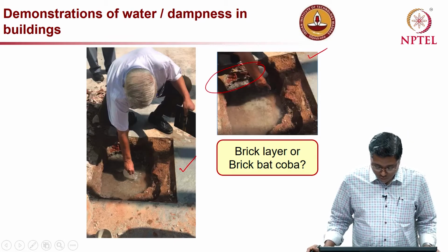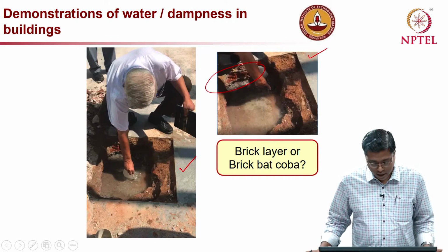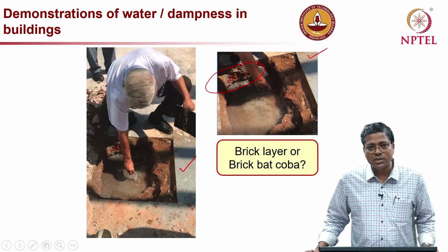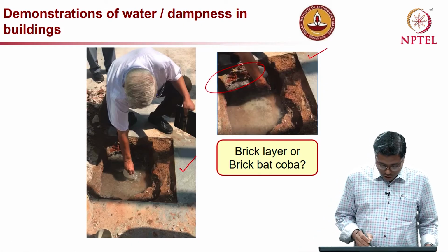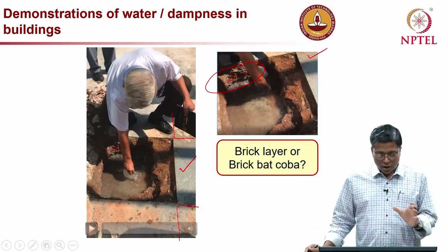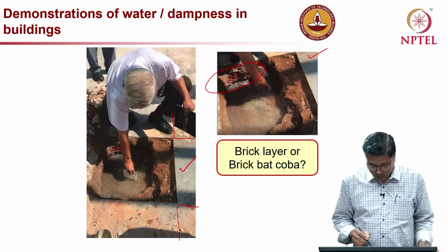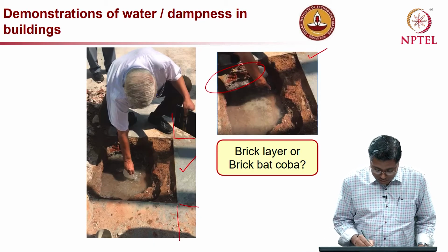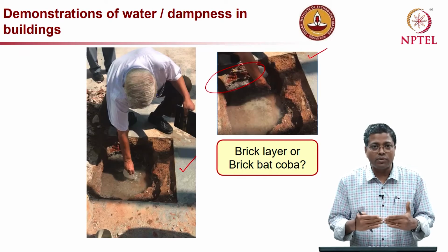I am going to show you this video to show how significant this problem can be. This video was taken just one day after a rain. All these joints between the tiles, as you can see here, were not so good, so water actually infiltrated through them. You can see very clearly that at these joints there is no gap, no visible filler material between the tiles.